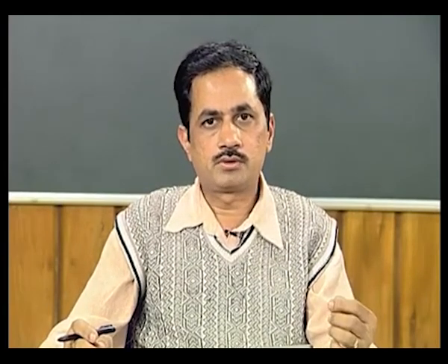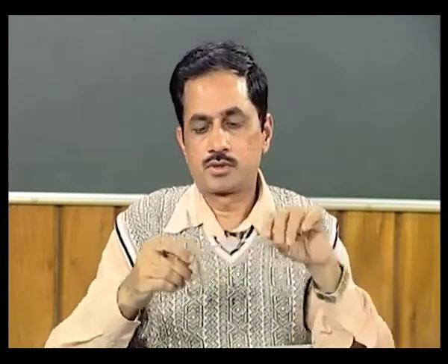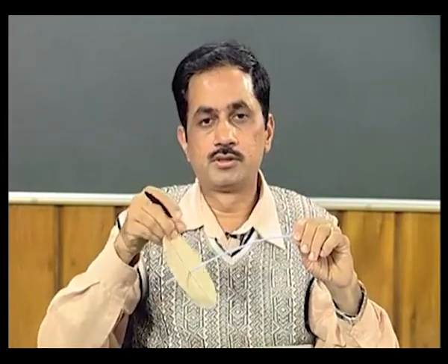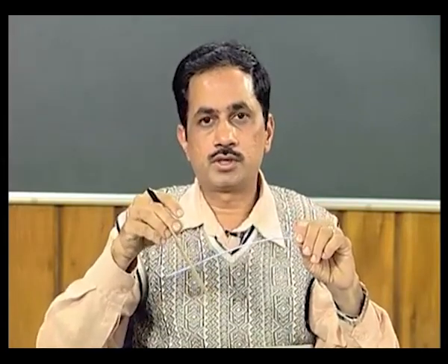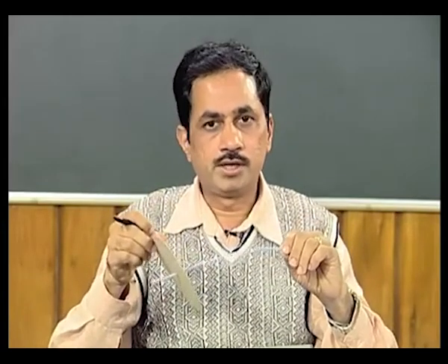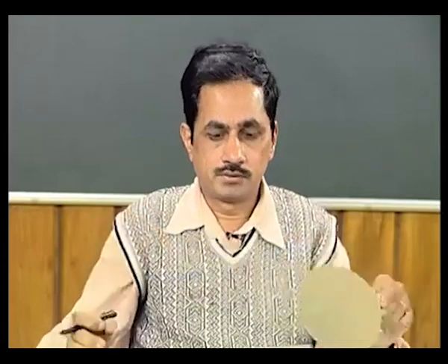Now, we can get the angular momentum of the disc, because this particular disc is tilting about its diameter, this diameter. So, for the angular momentum calculation we need to consider ID, the diametral mass moment of inertia, and we will be multiplying it with this velocity which we obtained. So, the angular momentum of this particular disc will be,